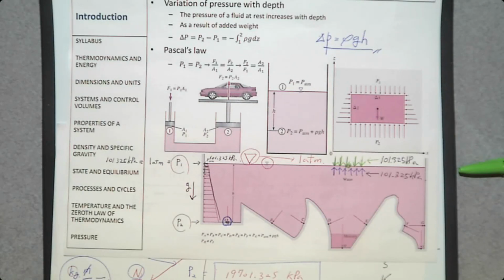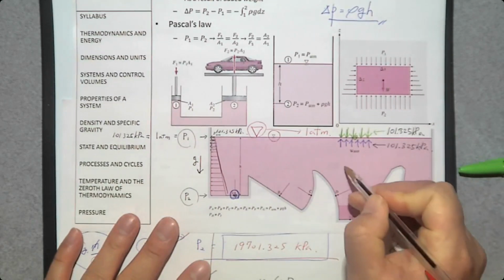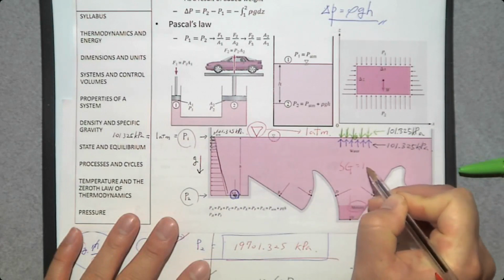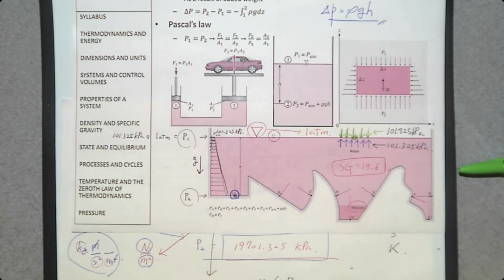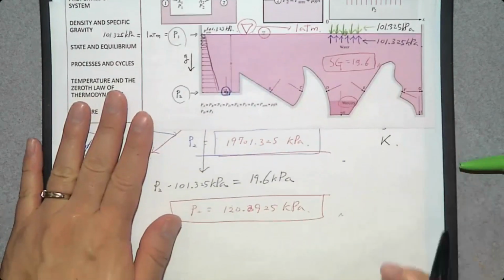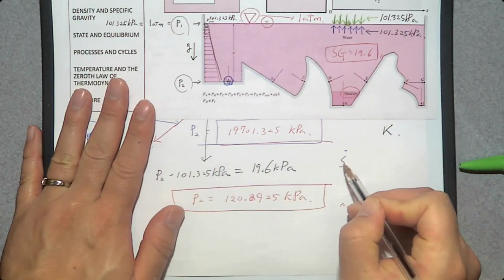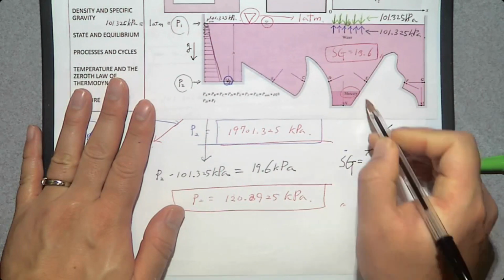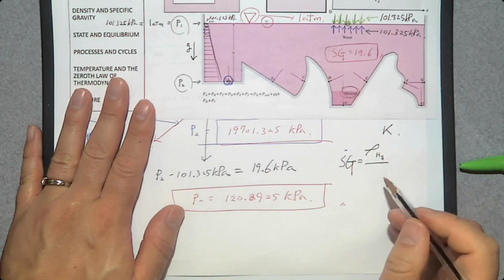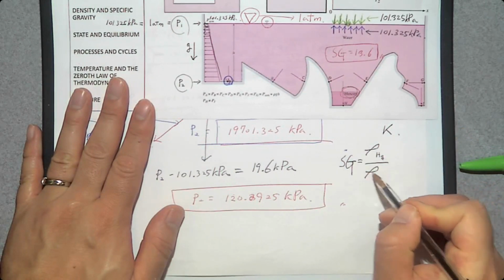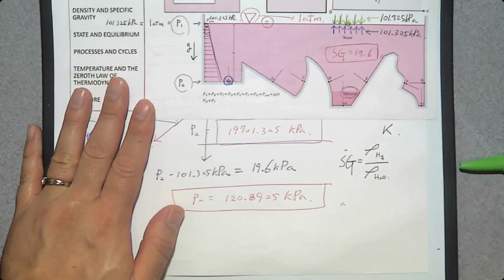And how heavy is mercury? What is the specific gravity of mercury? Specific gravity of mercury is 13.6. Then can you determine the density value when you know this specific gravity? Yes, you can, because specific gravity, SG, is the density of mercury, Hg, divided by the density of the standard substance, which is water at 4 degrees Celsius.